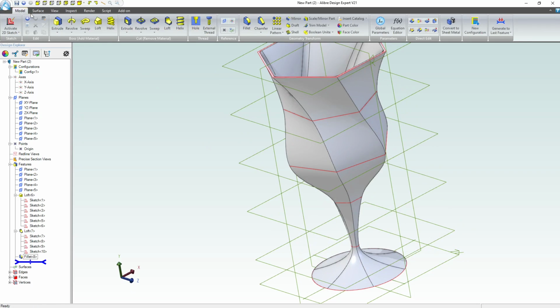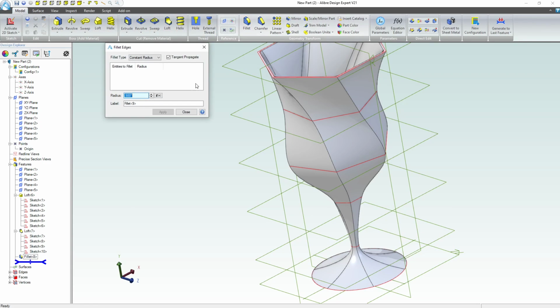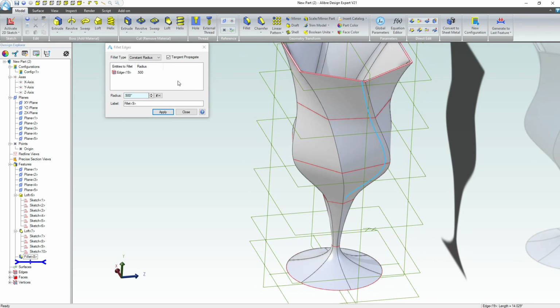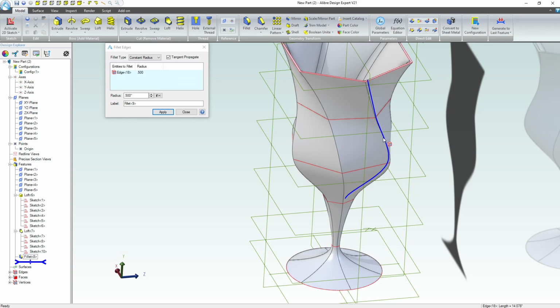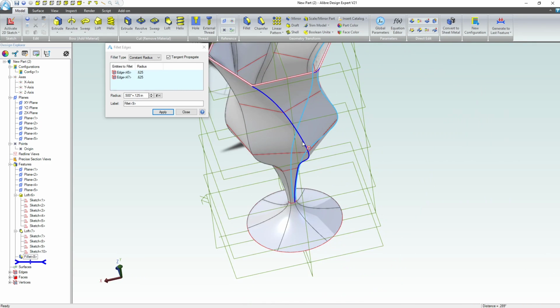Now, let's add in another fillet. That was a 1/2 inch, or an 1/8 inch thick, so plus 0.125. And that will give us a constant radius. And of course I chose the wrong edge. Let's try that one more time. Nope. That one. Thank you. Plus 0.125. See, these are so close together that it's easy to select the wrong edge. There we go.